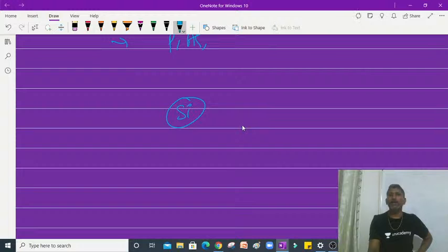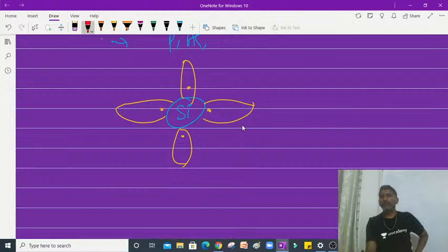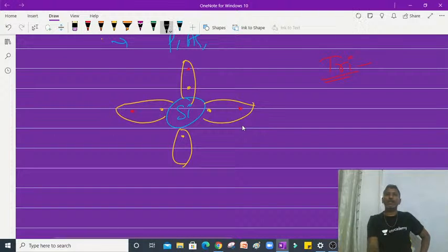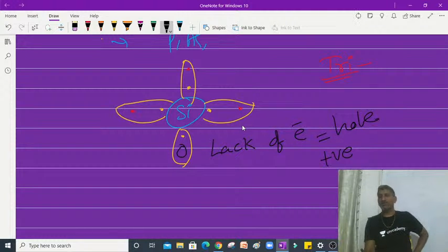Say this is silicon again. Now here it is having 4. Let me take this diagram once like this. Now the silicon is having 4 valence electrons, which we are showing in this way, in this diagram. And now suppose trivalent atoms we are adding. Tri means 3, right? So 1, 2, 3. Students, here you see 1 is left free. Means here there is a lagging. So lack of electron. What I can say? Lack of electron, which is called a hole, students. This hole can carry a positive charge. Hole behaves like a positive charge.